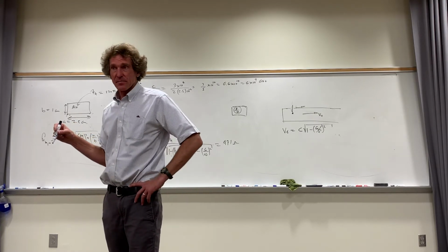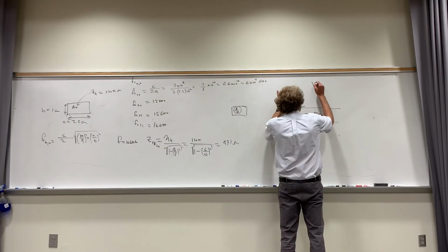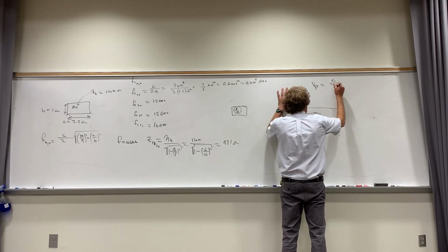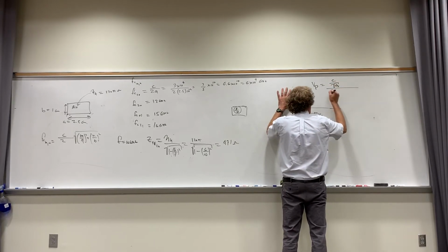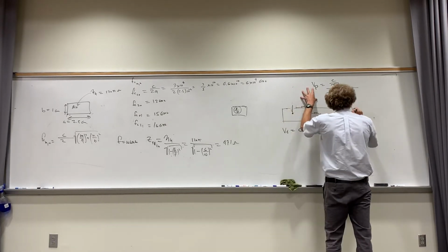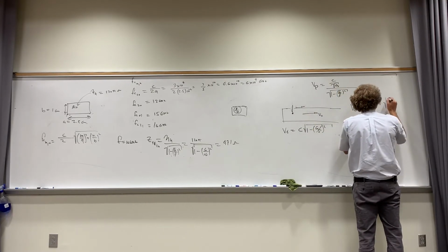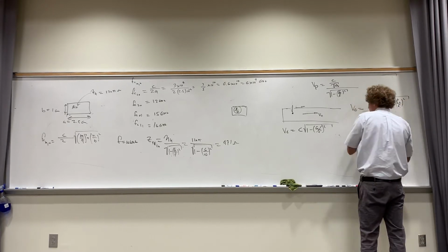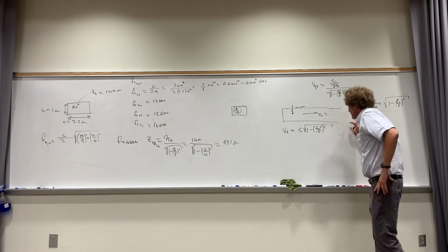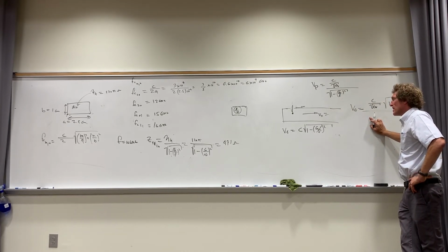Does everybody have that, class? If I didn't state it clear enough, realize this. Phase velocity will always be c over the square root of epsilon relative divided by the square root of 1 minus fc over f squared. That's phase. Energy will always be c over the square root of epsilon relative times the square root of 1 minus fc over f squared. So what is the speed of energy down there? Just tell me what 1 minus fc over f squared, square-rooted, is.